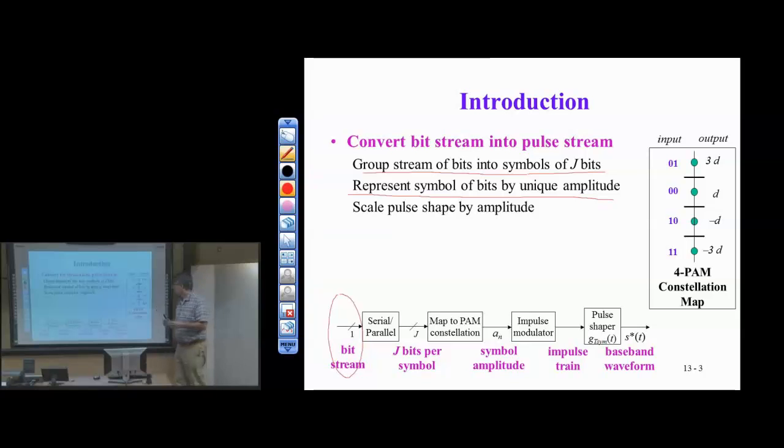Okay, so what I show on the right is an alphabet of 4 symbols. This would be the case for J equals 2, so 2 bits or 4 levels. I'm on the transmit side, so I'm going to take my symbol of capital J bits, here J is 2, and I can send 2 to the J symbols. And J can be large. In practice, J goes all the way up to 15 in DSL. It's a lot of possible symbols,